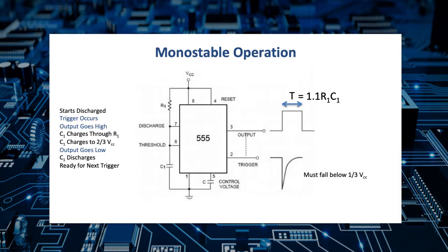And you can make that pulse as narrow or as wide as you want. Another important thing to note is that a 555 set up for monostable operation in this configuration will continue to trigger if it continues to receive trigger pulses. That is, if the output is high and a second trigger occurs while the output is high, then it will continue to stay high. And it will stay high until T time after the last trigger.